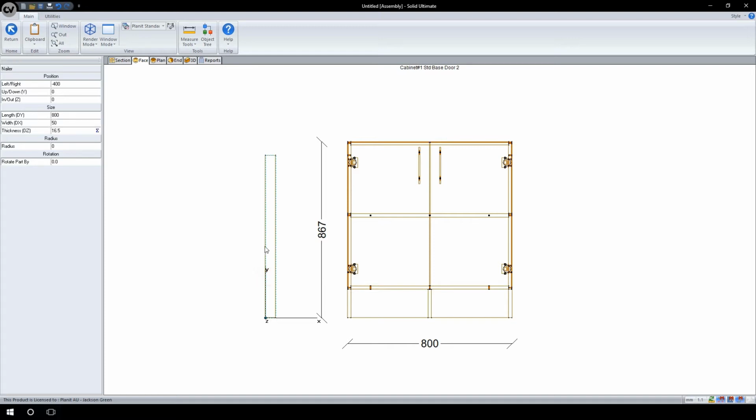Now rotate the part using the Rotate Part By. Seeing the axis lines here, this is how we establish where the origin point of this part is. Also, utilize the link in the description to understand the origin points of parts better. We will first focus on the placement of the part, which is the X, Y, and Z values. I want to first set the Z value.